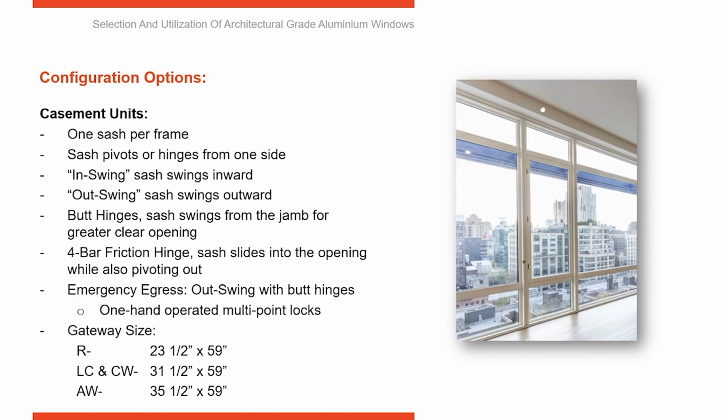There's a high-rise multifamily project. So if you notice on this one, the casement window has a cam handle at the bottom. You can see one cam handle, and the cam is kind of flipped up so you can see it. But that operates two remote locks that you can see further up the sides of the casement window. So in this case, you're going to have a single point multi-lock application, single handle multi-point operation. So the casement can be operated by one cam handle that releases three locks that are daisy linked to it.